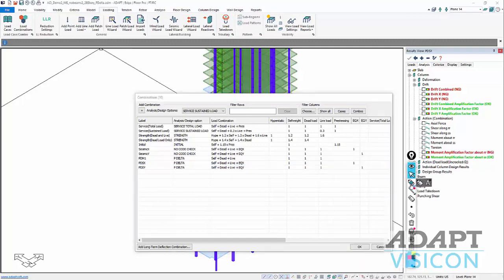Because these 3 sets of factors and load cases are identical, this first combination is designated as a master combination, meaning the program will generate a geometric stiffness matrix from that combination and then apply it to the solution for these 2 combinations.